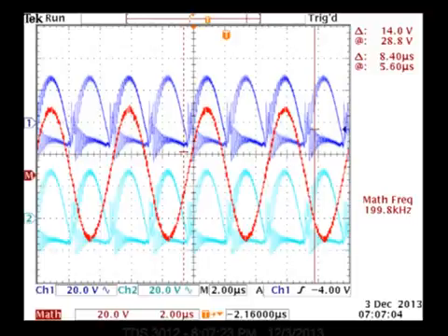After hooking up 2 power supplies in parallel and removing half the capacitors, the peak temperature we measured across a piece of heated steel was 500 degrees Fahrenheit. At that point, the highest resonant frequency was about 200 kilohertz.